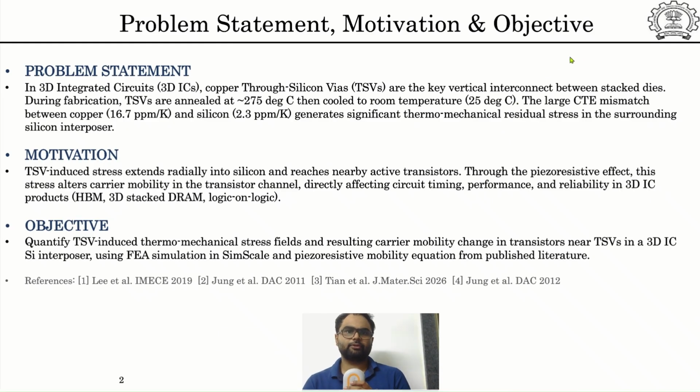So let's move to the second slide: problem statement, motivation and objective. So first, what is the problem statement? In 3D integrated circuits, TSV acts as a vertical interconnect between stacked dies. During fabrication, the TSV is heated to around 275 degrees Celsius and cooled down to room temperature. Because of the mismatch in thermal expansion between copper and silicon, a significant residual stress is generated in the surrounding region.